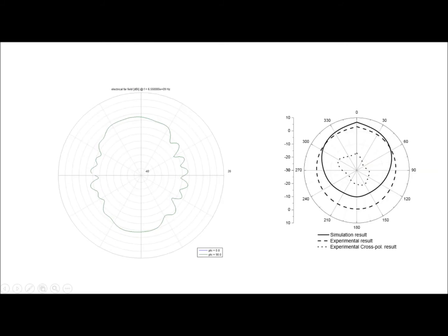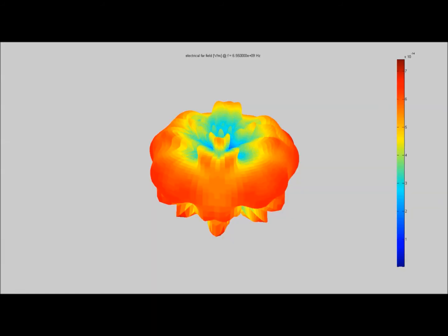Moving on to the far field graphs. A two-dimensional far field graph mirrors the symmetry of those in the paper. However, it's clear that it's not quite as smooth or as round as it should be. This could most probably be attributed to the proportional size of the coax excitation. However, as mentioned, decreasing the size of this excitation results in faulty running code.